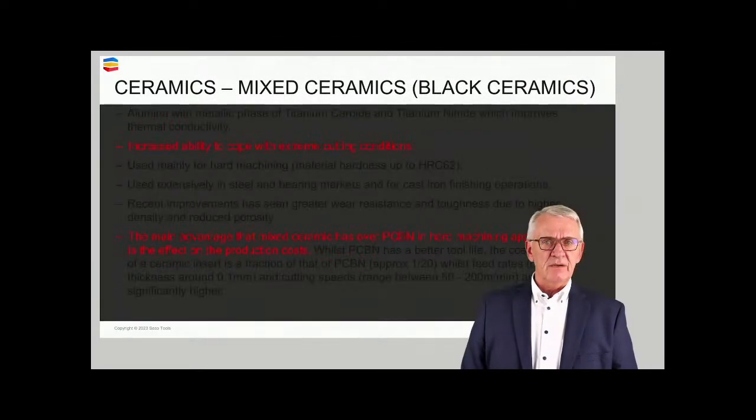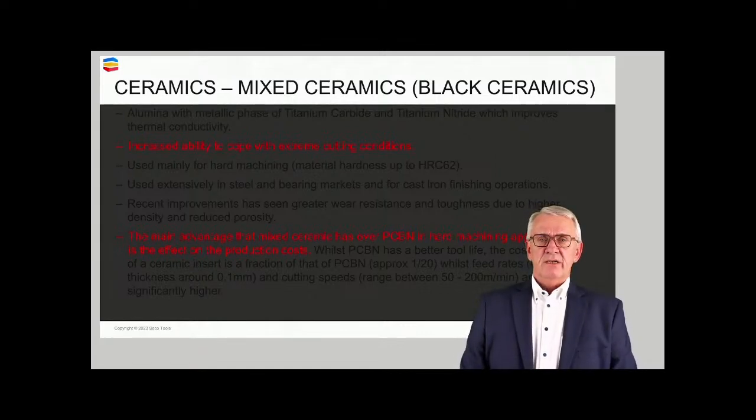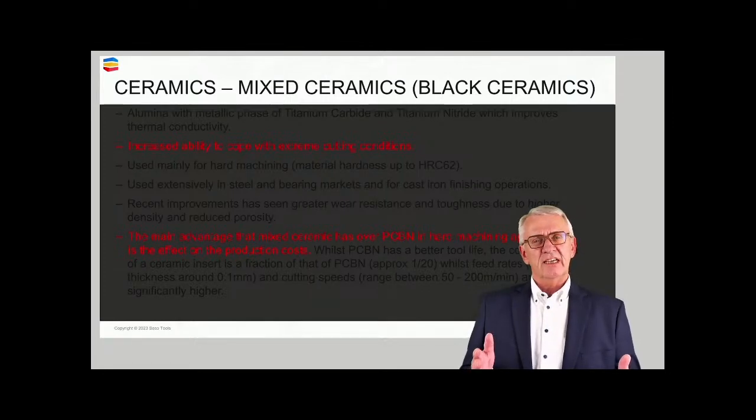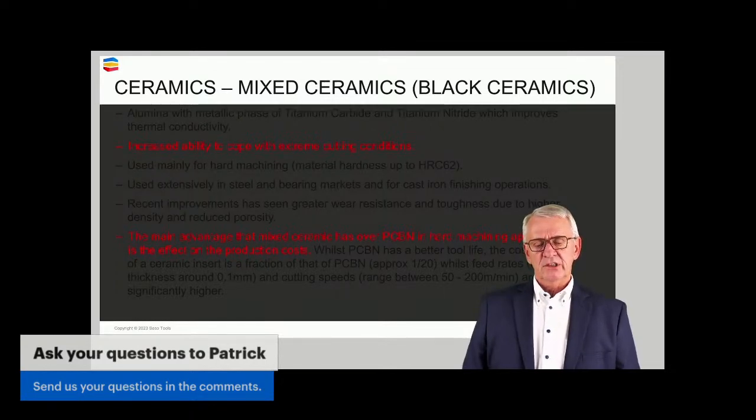Because you also have the mixed ceramics, black ceramics, which are compound materials. It's ceramic grains, one could say, with a binder material. The big advantage of black ceramics compared to white ceramics is that they can handle more extreme cutting conditions. The toughness is better. They are not so sensitive to breakage. Mixed ceramics, black ceramics, can be a serious competitor for PCBN in hard machining. But that's an evaluation you need to make not only based on technical considerations, but also on economical considerations.